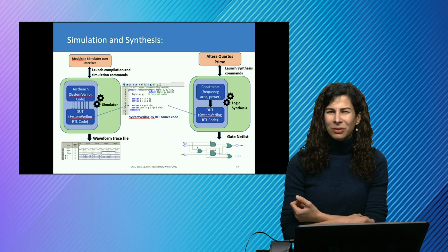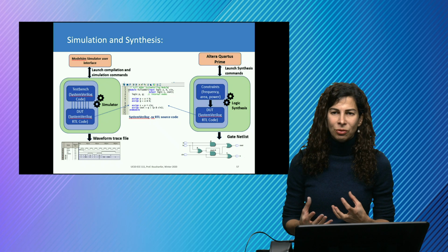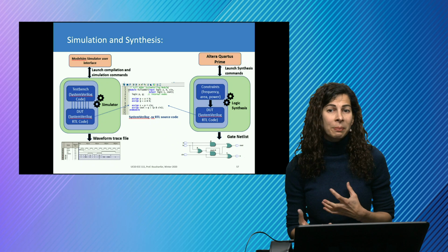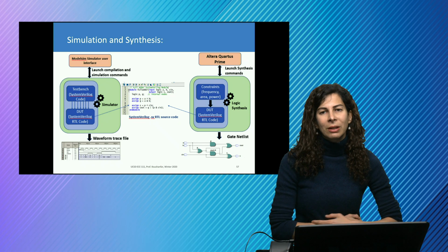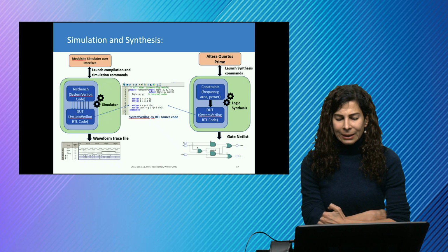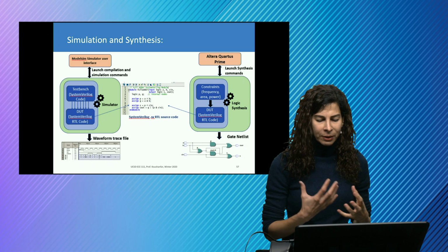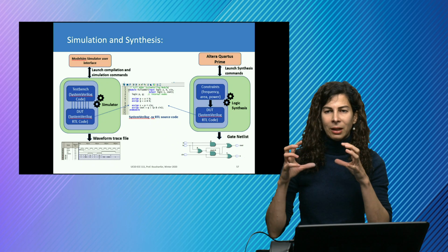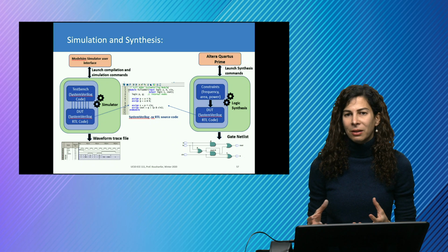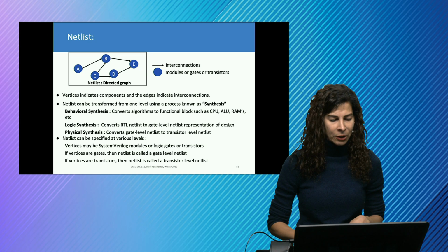What happens in typical design is that we give part of these design criteria as constraints, and then we try to optimize only one of them or a combination, for example, area-delay product, but giving one of them as a constraint. And the design under test is, again, part of the design where we define a real construct, such as a built-in self-test that we use in testing of the chips to test this piece of design in logic.